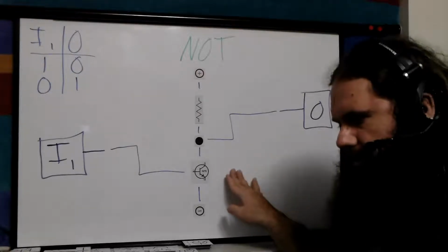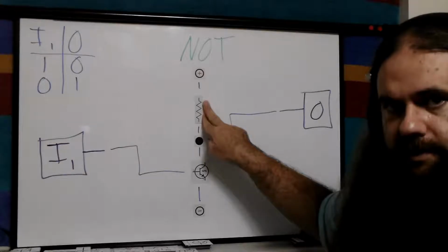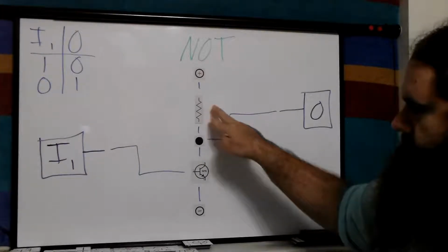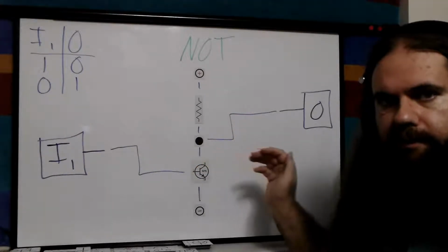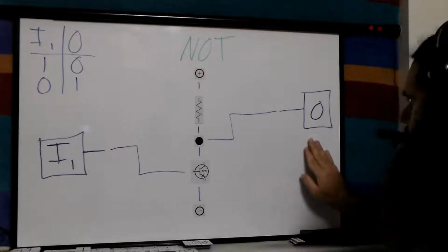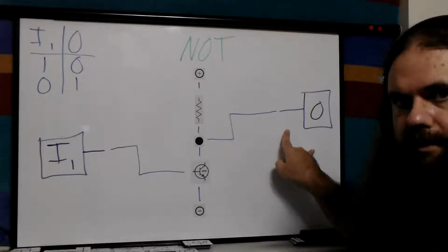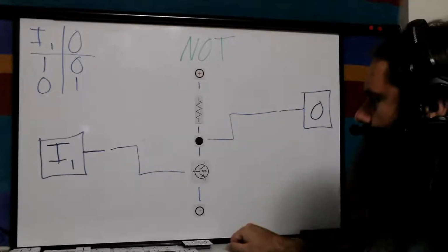Now, remember that the electric field establishes the voltage, and then from there, the resistor takes its voltage drop. The resistor is not a voltage drop on its own, like a transistor is. Ohmic devices are always proportional to whatever the rest of the circuit is doing. So let's say we had a transistor here, you would have the base to emitter junction dropping a small bit, probably connected directly to ground, and then you'd be sampling there, or whatever.